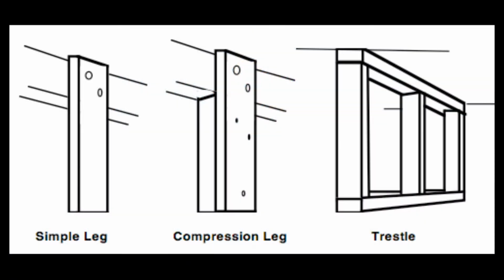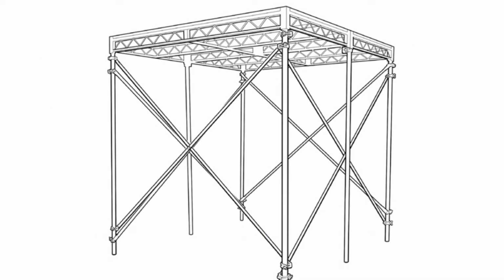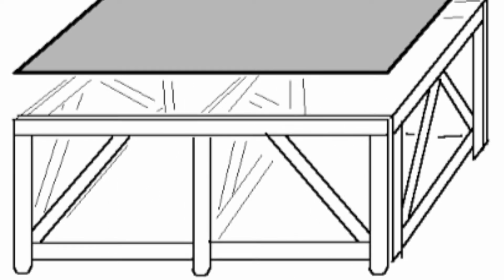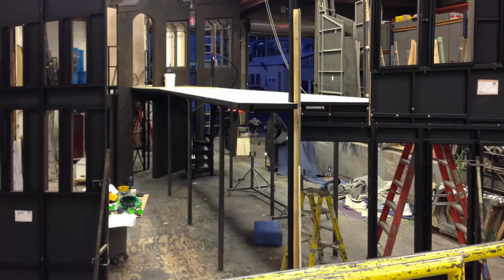Some of the more popular support structures include individual wooden legs and bracing, short wooden or steel stud walls, steel pipe legs and bracing, and collapsible frames. Each style has its own advantages. Long stud walls are quick to build, can be set up to support multiple platforms, and their continuous nature can help smooth over uneven stage flooring.